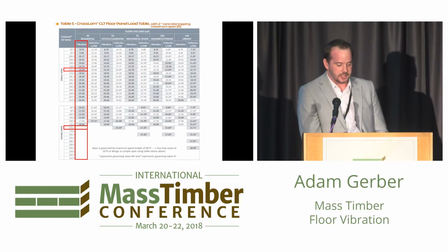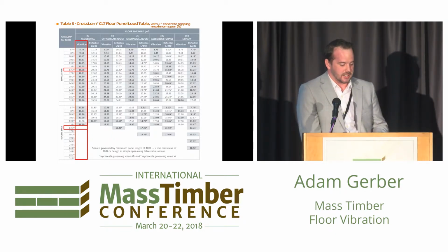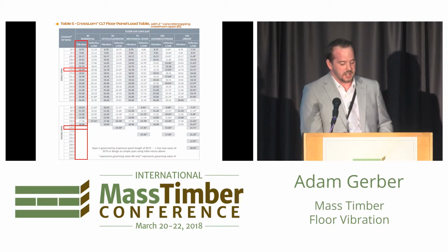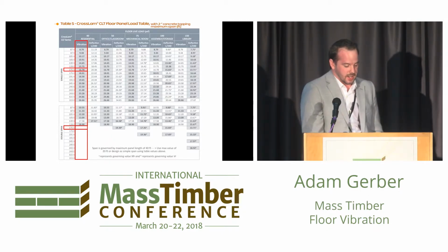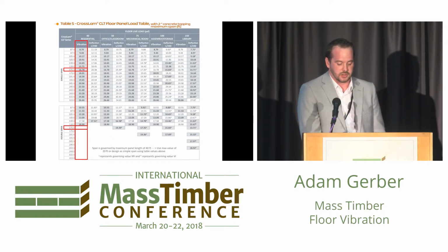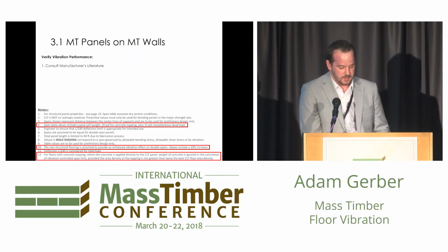So right out of the literature, we can see for the panel that we've selected, I've borrowed this table from StructureLam. They have some guidance on vibrations. And you can see that for a single span panel, it's not going to work, but as soon as you get into a double span continuous, it appears that it's governed by the panel size rather than the vibration controlled span. So it implies that we're good to go.